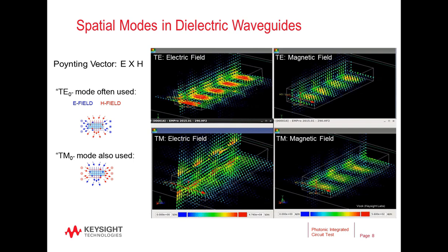Now that we have waveguides, we can visualize the modal propagation down these guides. Here we use EM Pro 3D modeling for the simulations. The guides typically support transverse electric, or TE modes, and transverse magnetic, or TM modes, though they may have been designed for just one mode, and the other mode may behave poorly. In the plots here, I guess the movies here, the TM mode is shown in the upper left simulation.